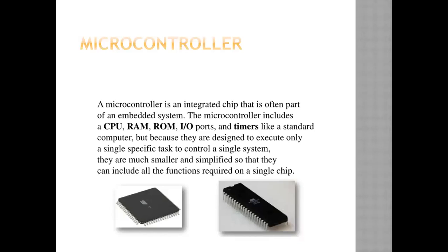Similarly, the microcontrollers we talk about now also have a CPU, random access memory (RAM), read-only memory (ROM), and I/O ports where I can attach external peripherals, and timers, like a standard computer. Timers are provided here to note events and keep the timing concurrent. These timers have their own counters where I can load a count depending on the delay required, so that the timer can execute the delays properly.